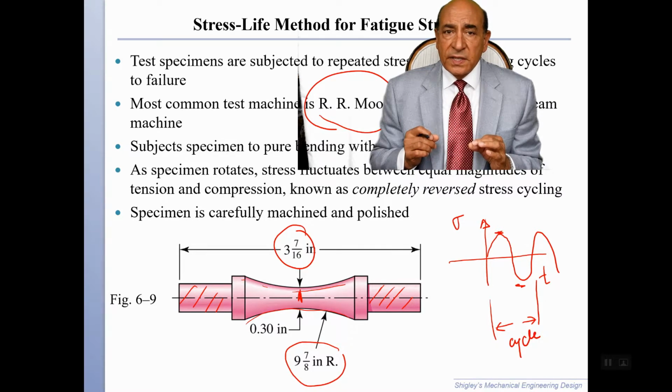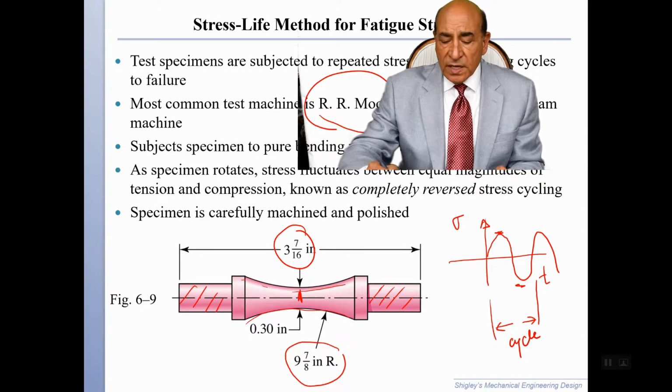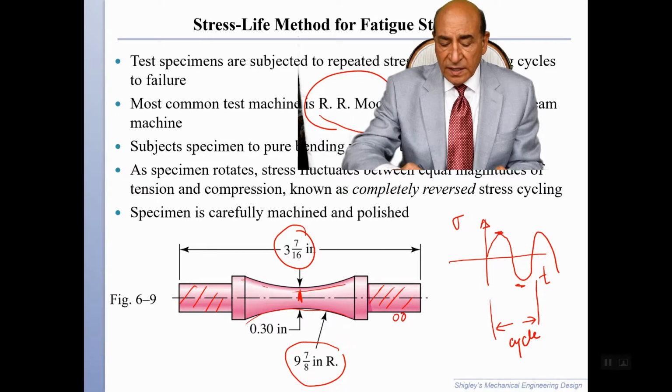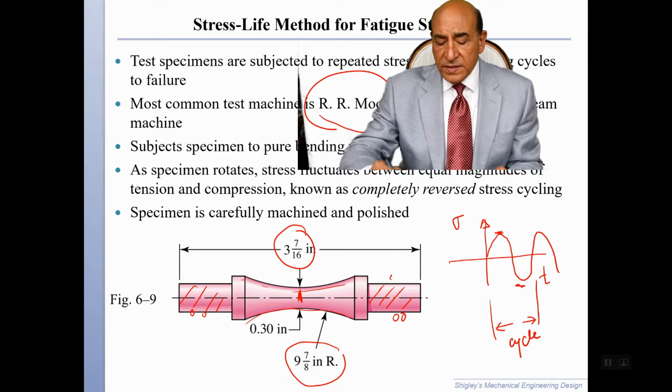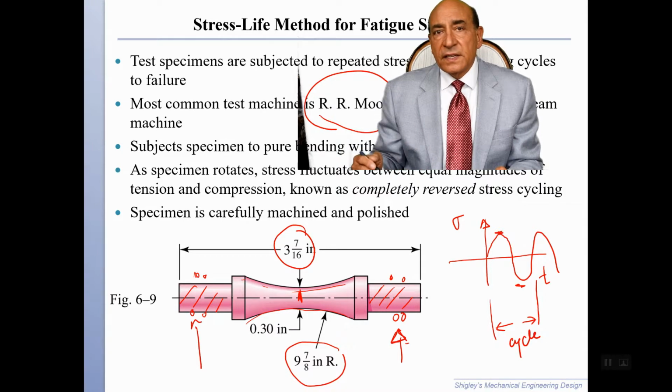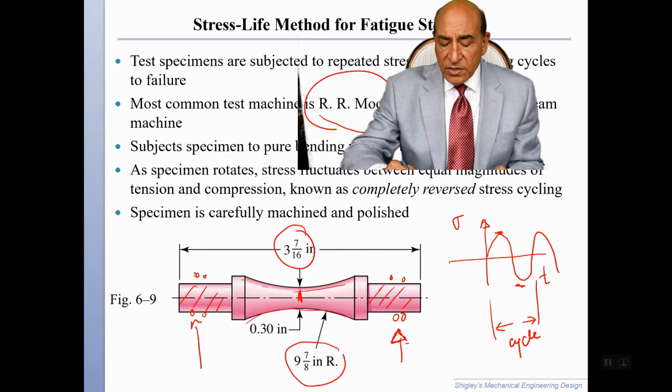embedded in a fatigue test machine that is known to induce stress reversal in the following way. We have ball bearings on these ends of the sample, and the ball bearings induce a reaction force on this side and a reaction force on this side, and there's a load imposed on the material.